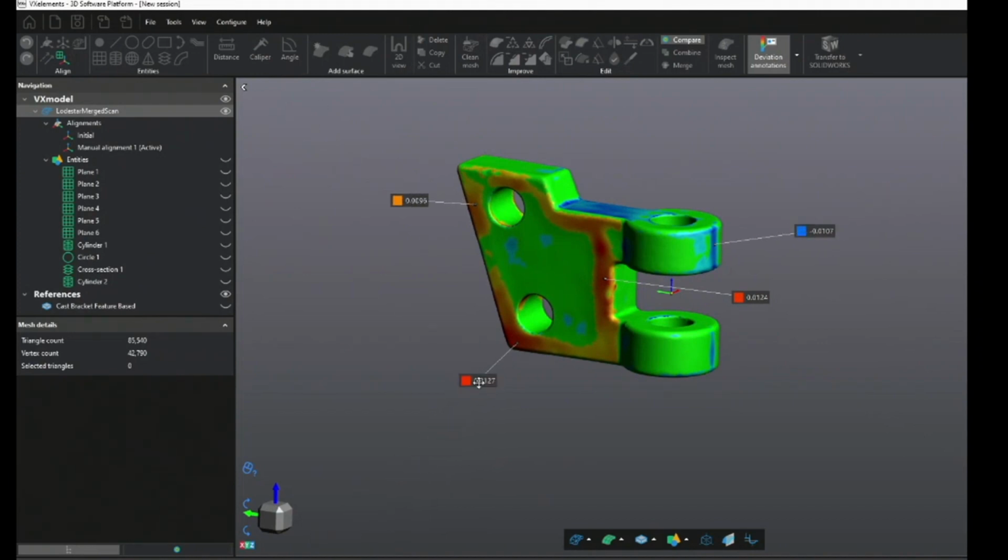Yeah, when you deliver the finished product to your customer, you want to be able to demonstrate to them how that model compares to the original, and just verify with them that the model is what they want. Say, I made a best fit plane on the right-hand side of this part. You can see that the part actually has a small sink mark here and is proud around the edges. So in the casting process, the material has sunk down in the center and is still raised on the edges here.